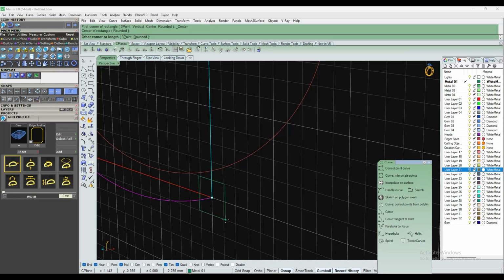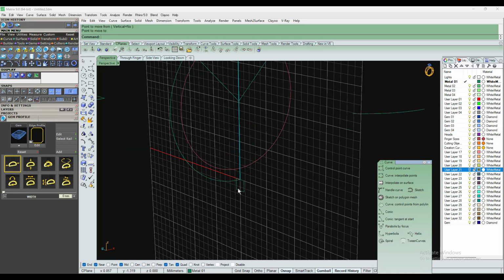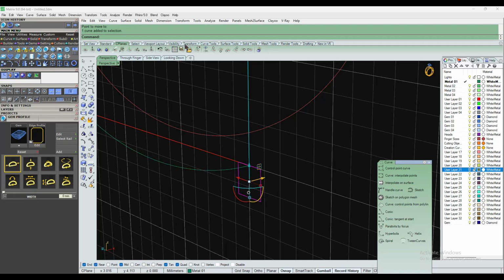For right now, specify 1.5 as a height, and let's make 1.3 as the thickness. Let's make 1.5 by 1.5, and then use the move option and bring this here. Oops, the C plane is here. Sorry, the inside rail is here. So let's move this point to this point.